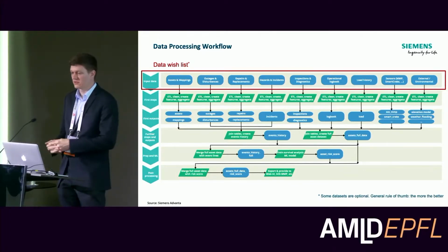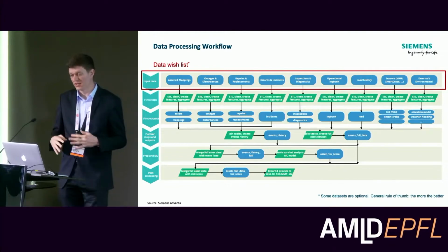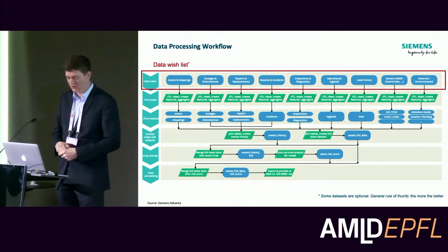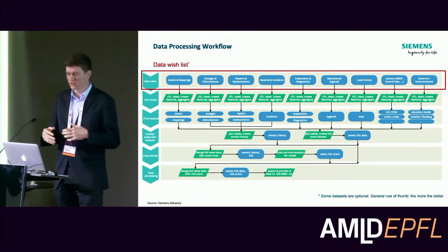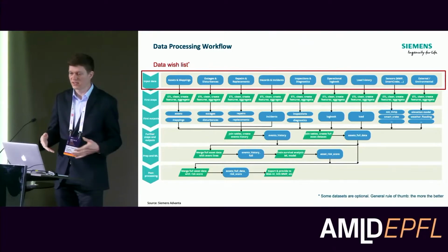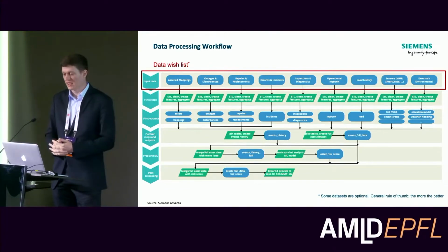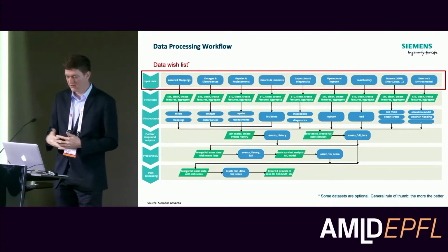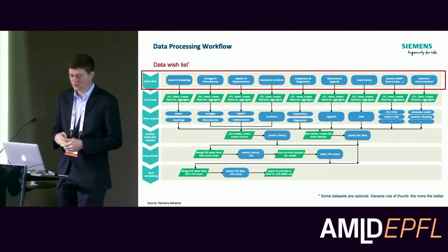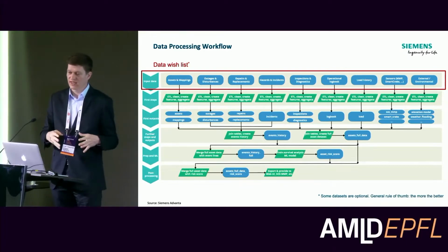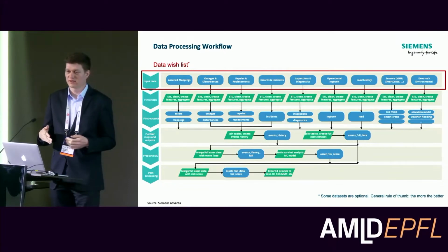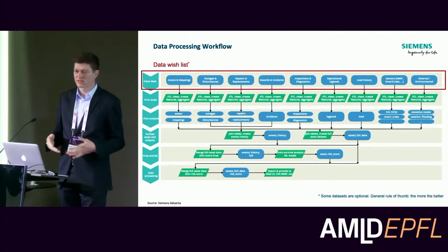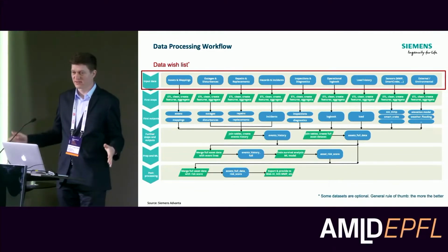Operational logbook, so what was the past load on which cable section, is sometimes quite difficult to obtain, more difficult than you may think. And then there are also sensors. Typically we try to get as far as possible without putting in new sensors, because then we can start right away. The model will not be perfect in prediction accuracy, but in the US project we see that they already have sensors in the grid, but the sensors will be at the end of life soon. So that's also a problem if you're looking at transformers and cables. These assets stay there for 50 years, maybe 70 years.